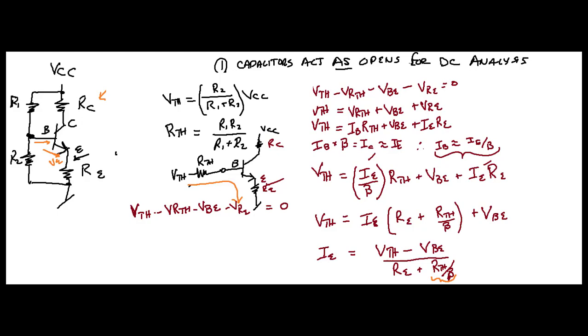So this is what the discussion is, or the logic behind it. Generally RTH, your Thevenin resistance, divided by beta, which is usually 100 to 200 or more, depending on what your resistor is, is considered very small and almost insignificant. So many times that's ignored, and that's why you don't see it. But there's two ways to calculate it. Just be aware that if it's not insignificant, you need to include it, okay? So that is a discussion. That's the second way of doing it.